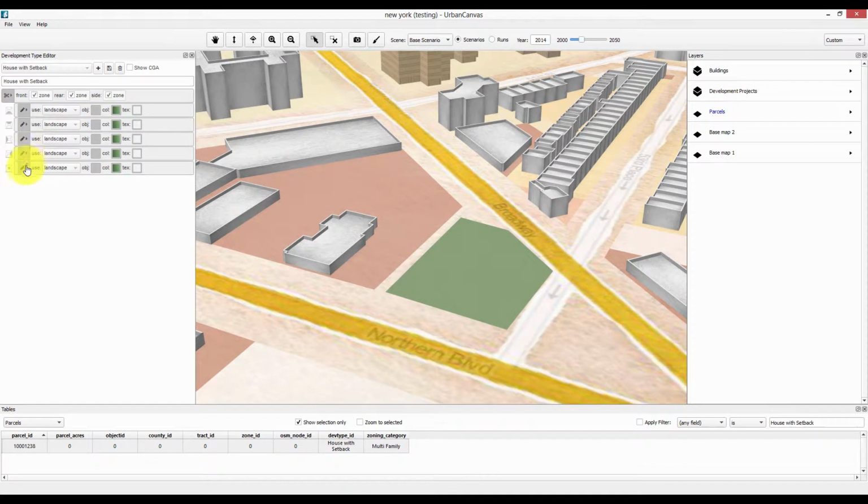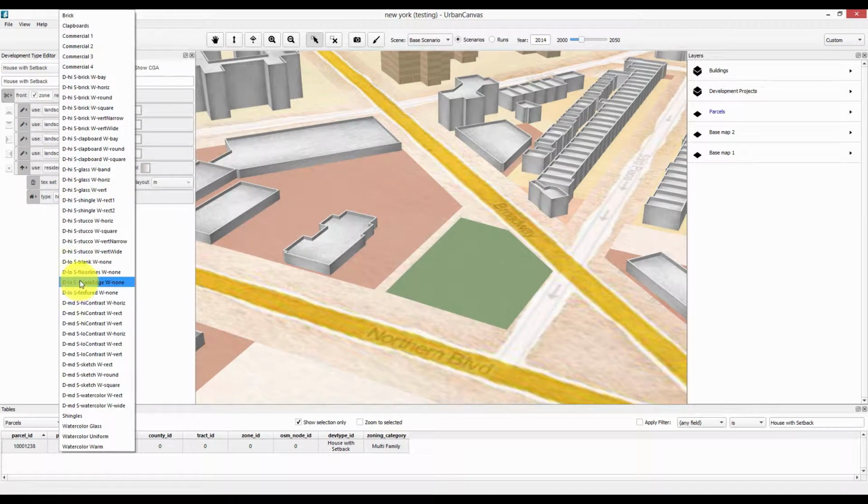Now we will extrude the inner shape to the number of stories specified in the building table. We will cap it with a hip roof. We'll add a texture set to the faces of the extrusion from the many choices in the menu, as well as layout style for the texture. You can try different combinations of texture set and layout to find one that is appropriate for your purpose. Here we select one with a moderate level of detail. Different styles with higher and lower detail are also available.